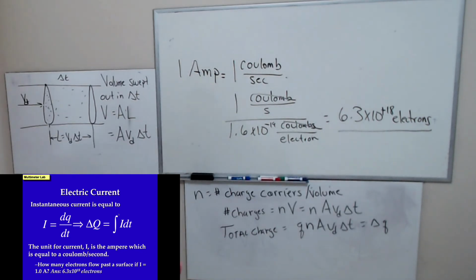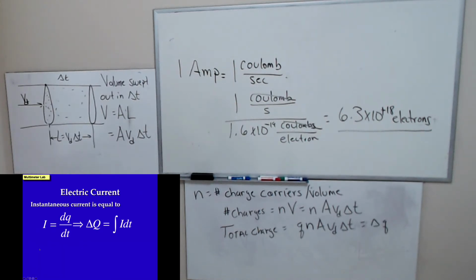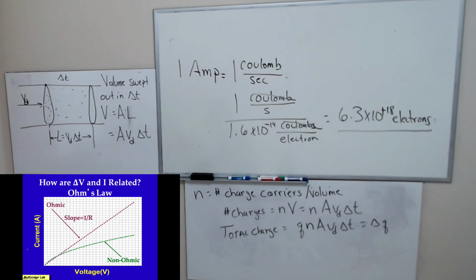And because you have that many electrons going through your wire, you have all those electrons colliding and dumping their energy into the wire. So when you have a large current and it's dumping electrical energy into the material, it will warm up. That's why wires have limitations in terms of how much current they can carry. The more current, the thicker the wire has to be. Okay.